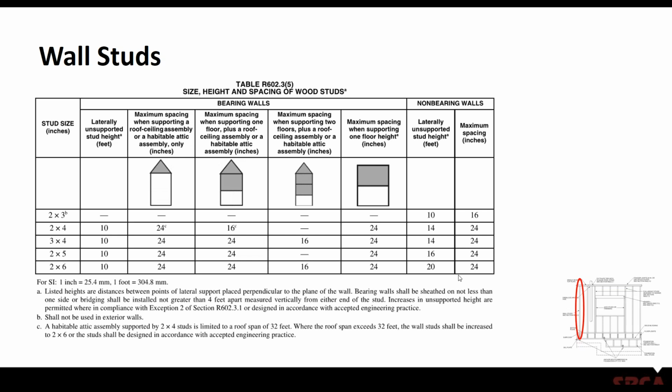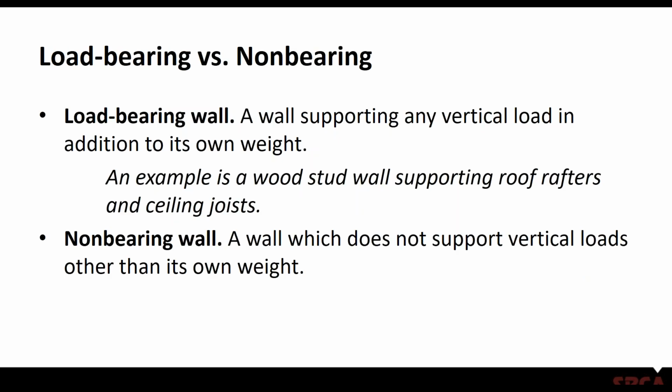And then obviously if it's a non-bearing wall, you're allowed to go taller. But again, based on that exception, you are allowed to go with a taller wall, but it's very limited in terms of how much load that can support. And I know there are certainly some homes out there with great rooms in which the studs in those outside walls do not meet that exception we just read.